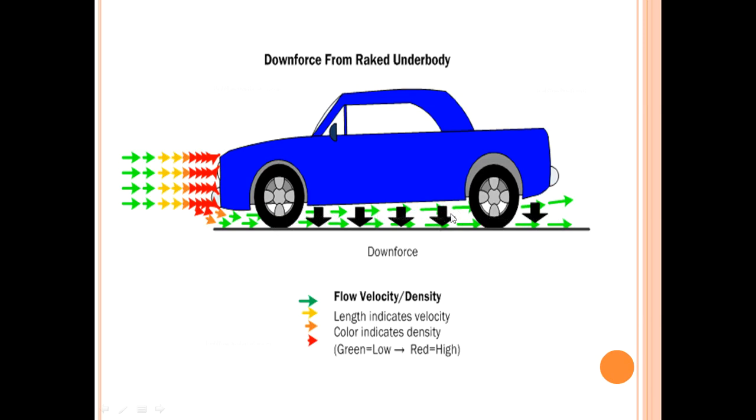When these air molecules are accelerated, or when their velocity is increased, the pressure will be decreased. We can conclude that from Bernoulli's principle. So when the velocity is increased, the pressure is decreased, and when the pressure is decreased, it will act as a downforce on the vehicle.